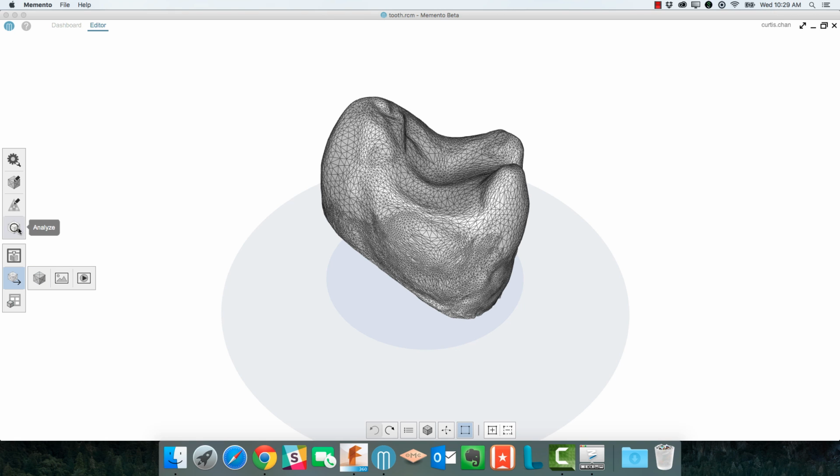One thing I do want to point out is that if you get some bad mesh data, some bad scan data, under Analyze, you can do Detect and Fix. The key here is under Advanced, I like to detect for particles, intersections, holes, and we can go through and do a quick detection. If there are any holes, you can go through and repair the holes. So you get a lot of flexibility here. Very, very simple. It's kind of like the easy button, right?